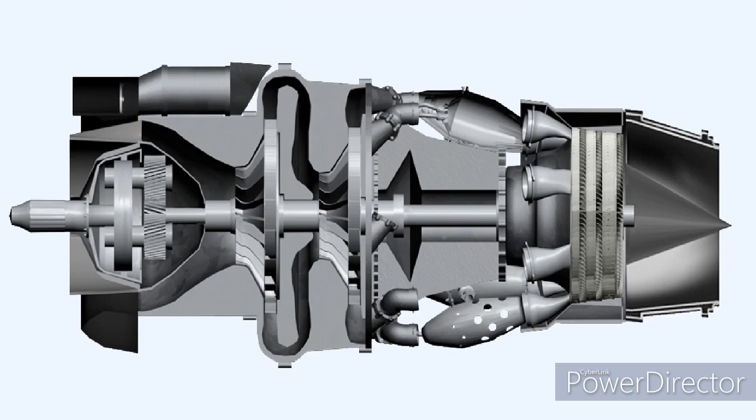In practice, it's not been found feasible to use more than 2 centrifugal compressor stages together. Excessive impeller tip speeds and extreme centrifugal loading prohibit efficient operation of a 3rd stage. As a result of this, engine compression ratios of much greater than 12:1 are not considered possible using centrifugal compressors.